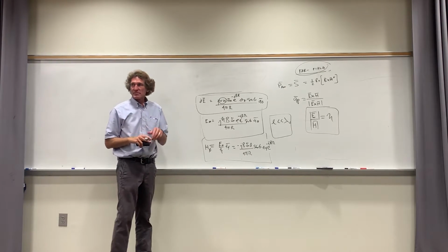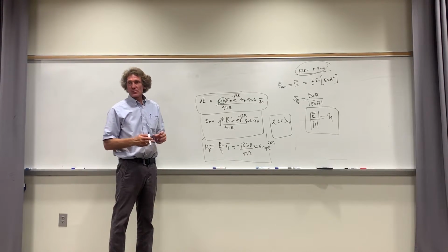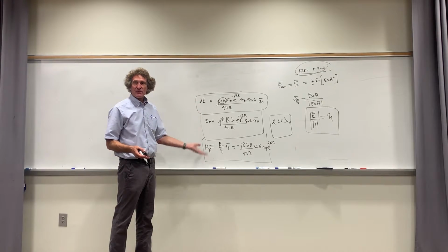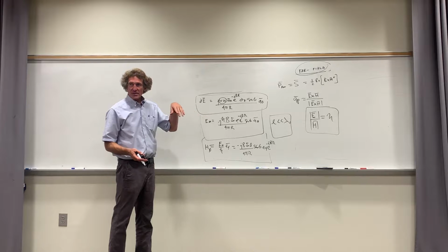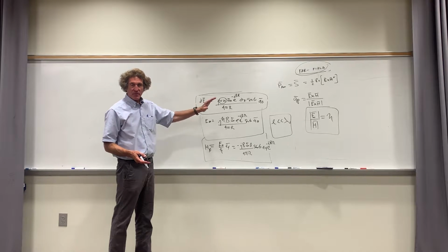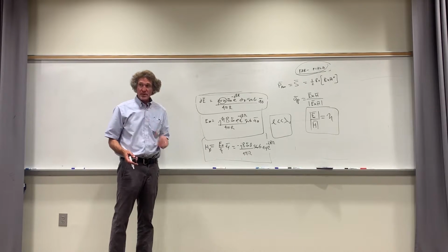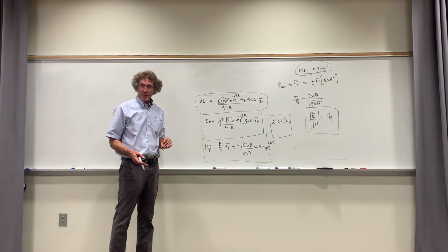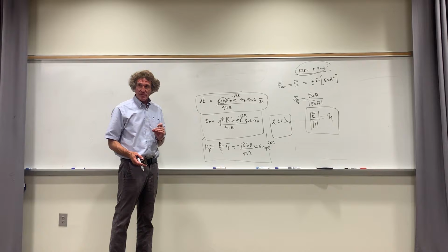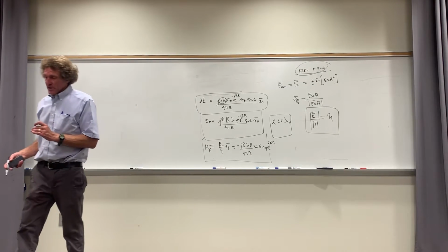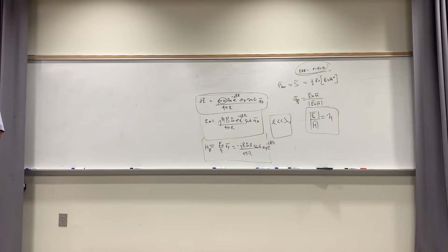And you know, I'm not too old to remember when I was in your shoes, a lot of this stuff seems really far away, abstract. You don't see the practical application of it, but you will. Remember these two equations for short pieces of wire with current. By short, I mean electrically short, much less than a wavelength, with current in it. This, believe it or not, really is applicable to a large class of simple antenna systems.